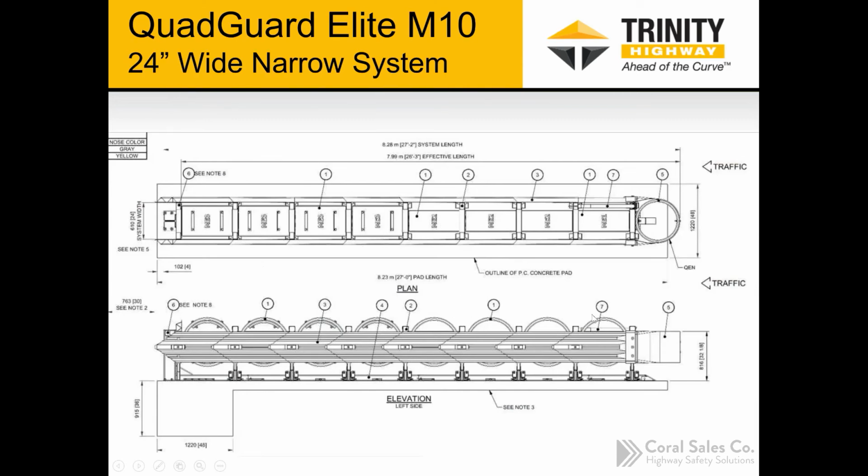You can see the front of the system has a lighter wall cylinder. Then toward the back of the system, we have heavier cylinders with laminates inside them. Those are designed to absorb the energy and resist the vehicle traveling into it at up to 62 miles an hour. They're labeled as 3 different types of cylinders: an ME1 in the front bay, and there's also a cylinder in the nose that absorbs some energy. This ME1 cylinder is the same cylinder as ME2.